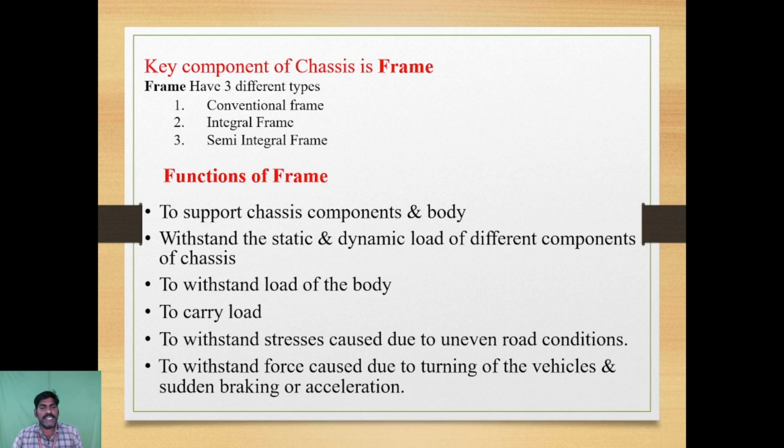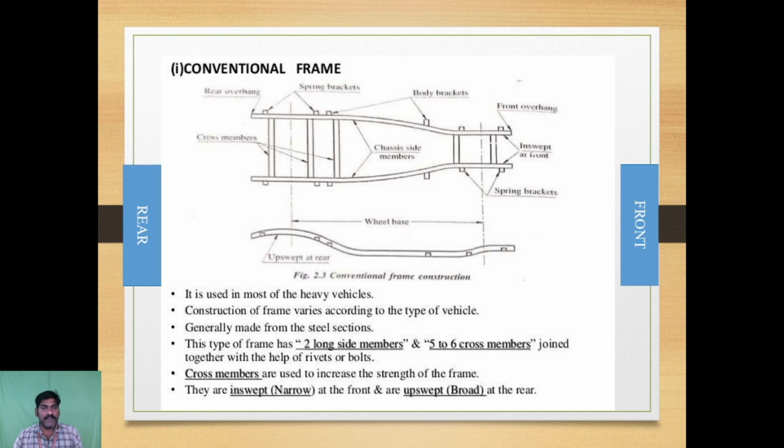Another topic: functions of the frame. First, to support the chassis components and body. Second, to withstand the static and dynamic loads of the different components of the chassis. Third, to withstand the load of the body, to carry the load. Fourth, to withstand stresses caused by uneven road conditions. Fifth, to withstand forces caused by turning of the vehicle and sudden braking or acceleration.